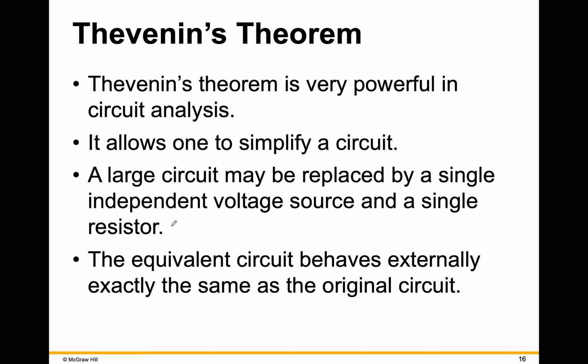There's a way to do this on Multisim in order to check. The way you would do it on Multisim is measure the open circuit voltage at a pair of terminals, and then put a short between the two terminals and ask Multisim to find the current through that short. That is finding the open circuit voltage and short circuit current. Right now, many of you are still struggling with the basic rules for solving circuits, but at some point, some of these problems you can certainly put into Multisim and get it to simulate for you so that you can see at the very least whether or not you have the correct answer.